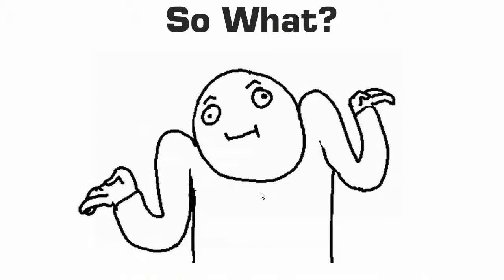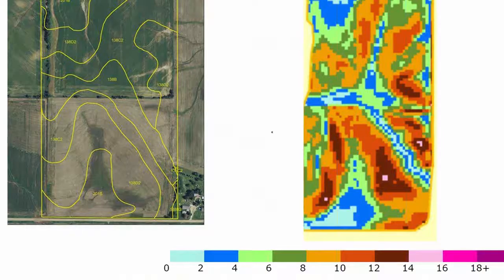We actually took a soils map, and on the right is a map showing slope data based off of LIDAR. So now you can take a look at, let's say, this 138C2 going in through here, and we can compare that over to here, and we have slopes ranging all over. We have some that are 4 to 6, some that are 6 to 8, some that are even 12 to 14, all within a C slope, which is 5 to 9% slope.